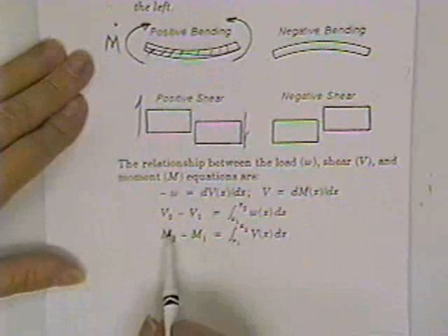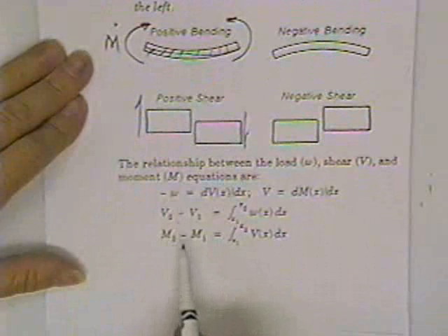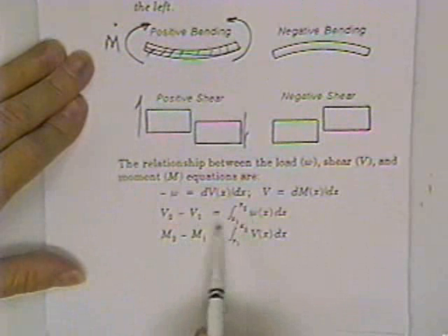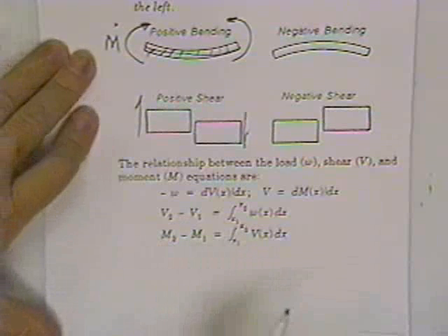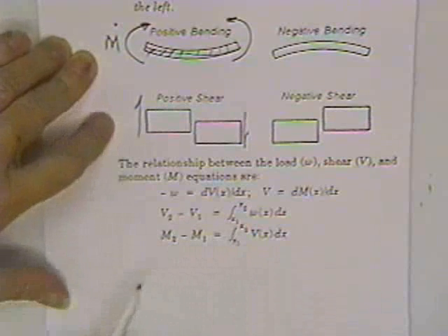There is a relationship between load, shear, and moment. All you got to do is you integrate the load, you get the change in shear. You integrate the shear, you get the change in moment. We'll show you how to use that in a minute.